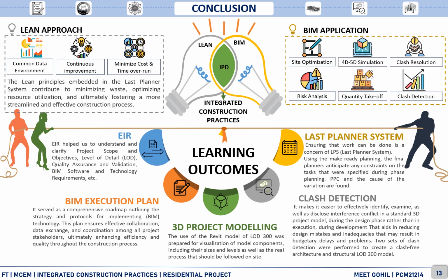Talking about clash detection, it makes it easier to efficiently identify, examine, as well as disclose interference conflicts in a standard 3D project model during the design phase rather than execution. During development, that aids in reducing design mistakes and inadequacies that may result in budgetary delays and problems. Two sets of clash detection were performed to create clash-free architectural and structural level of detail 300 models.